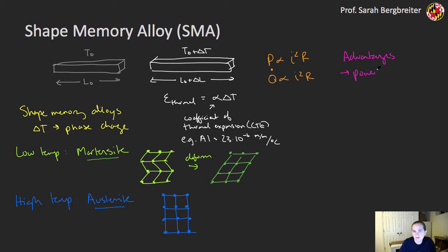A big one is going to be in power and force per mass of actuator, or I can think of that as specific power or specific force for the actuator, or watt per kilogram or newton per kilogram for this particular actuator. And these are often used in situations where I really care a lot about, for example, the mass of the actuator.